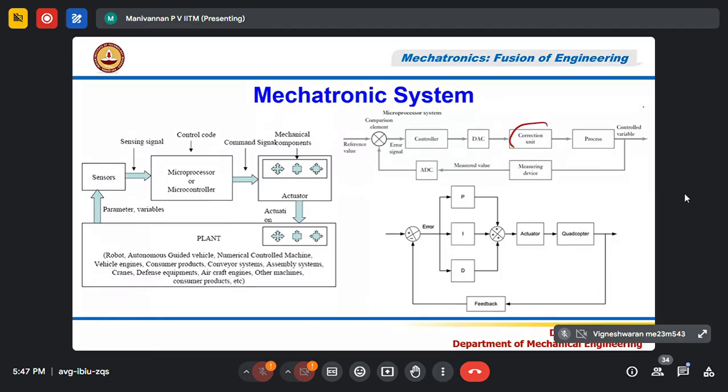Actuators, generally 99% of them, want an analog control signal. A motor, an engine, a jet engine, or a servo, for example a hydraulic motor, generally wants a continuous analog control signal. The computer generates a binary number, so that cannot be applied directly. Then you need a DAC.